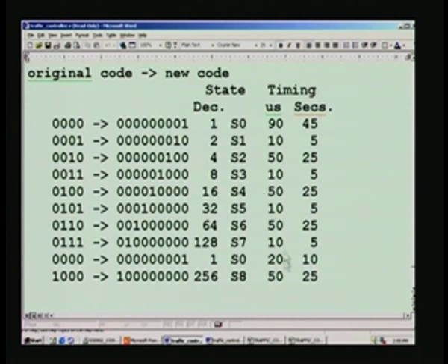So these are all the timings which we are going to see, and the corresponding actual time that we need is 45 seconds. This 90 microseconds you can interpret as 45, and you can see this ratio is maintained all through. So this will prove that all the counters are working precisely. In fact, only for the very first clock there is a 50 nanosecond error, I suppose, I am not very sure, but as far as the output is concerned, even that 50 nanosecond error is not there.